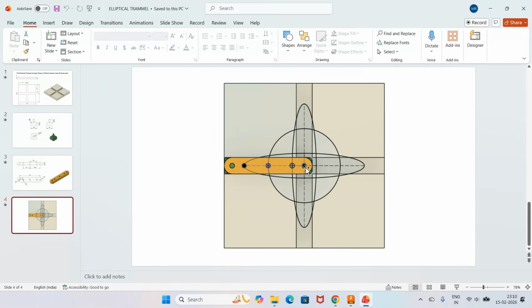One path is the distance between the center to this is exactly at the midpoint or the center of the link. Then the path traced is a circle. And if it is near to the center, in the vertical direction, it forms an ellipse. If it is in the horizontal direction, along the horizontal axis from the center, again it will form an ellipse.